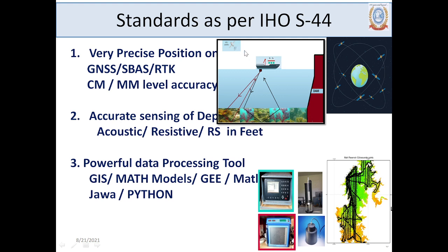The concept is that position information is very precisely acquired by the boat. The boat is on the move, because it is not going to stand still while taking the measurement. It is fitted with an echo sounder at the bottom, and a software controls the whole process. The echo sounder transmits the sound beam, and as the boat moves, the sound beam goes, touches the floor and comes back. Some sound gets reflected at this particular point, some goes down, some goes to the bottom. So what you see as a graphical output after the measurement is not the original, it is processed data.